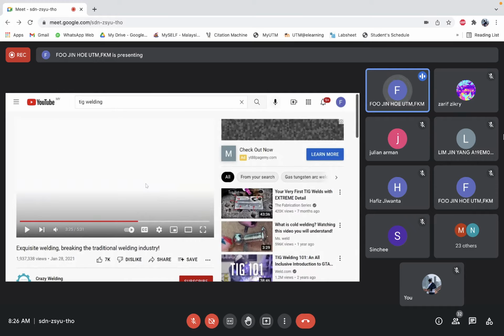Okay, if you notice that there are some of these MIG, basically they put, even though it's a consumable electrode, however, they use this wire rod, right? You can see they use the wire in the video just now. So sometimes when you are about to cover this, let's say there's a big hole, whereby you require a lot of this metal, this wire rod basically acts as this extra material, to give more material rather than you consuming the whole rod, just to fill up the hole. All right.